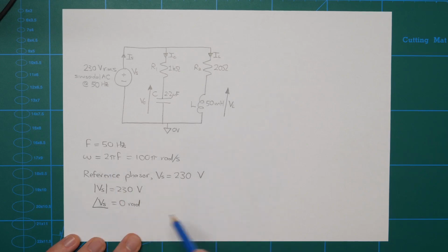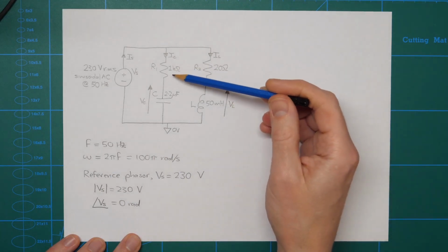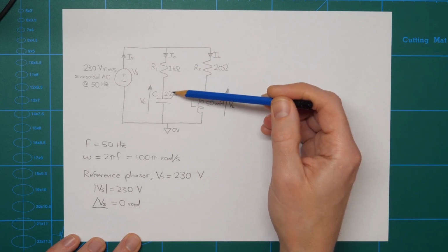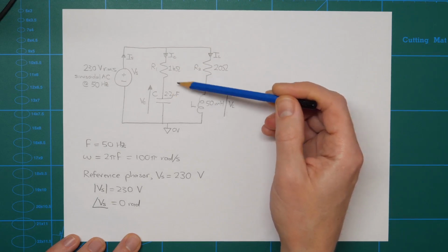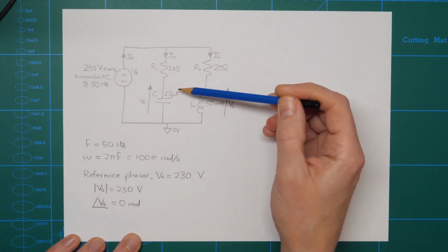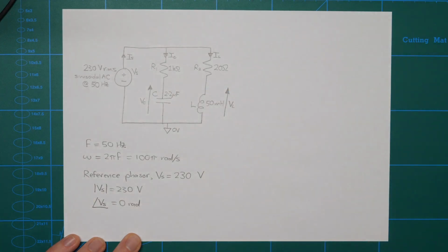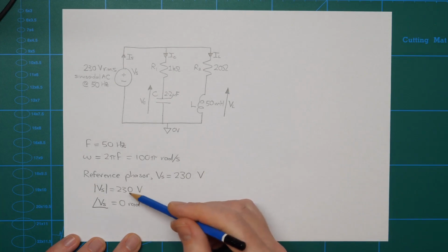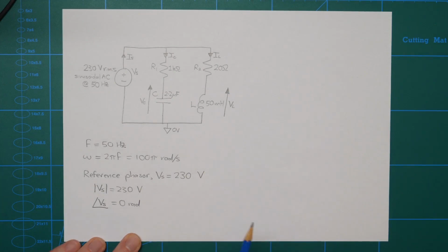Because all of the other phasors typically are going to have values that aren't purely real, some of them are going to be imaginary, and some a mixture of real and imaginary, full-blown complex numbers, it's best to think of each of the phasors as a complex number, even the ones that happen to have 0 real part or 0 angle.